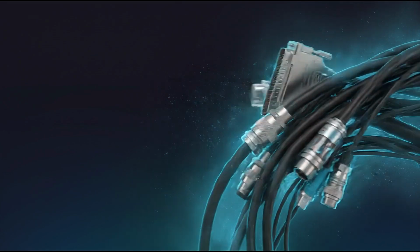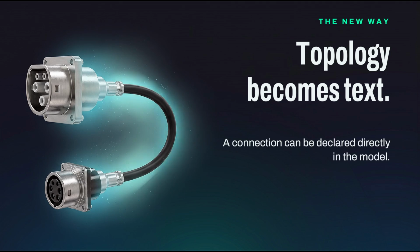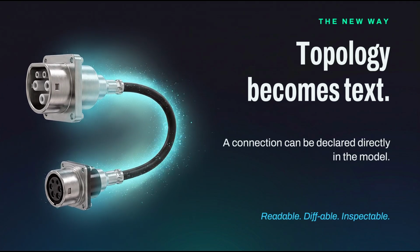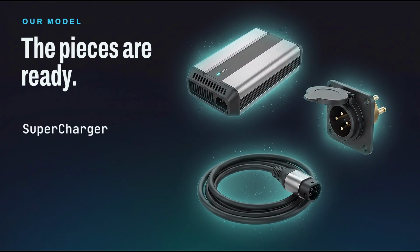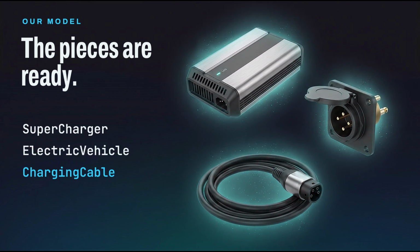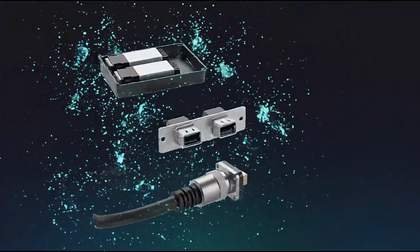SysML v2 makes topology explicit in the model text. A connection can be declared directly, which means the architecture becomes readable, diffable, and easier to inspect without depending only on a diagram. For our charging example, we already have the ingredients: a supercharger, an electric vehicle, and a charging cable interface definition. Now we need a charging station context where the charger and the vehicle are actually wired together.